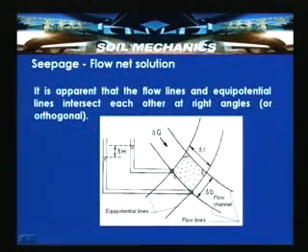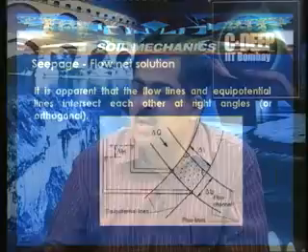So, here the drop which is taking place for a distance delta L for flow to take place is around delta H. So, we can also say that the hydraulic gradient is now delta H by delta L. For steady state seepage conditions, i is equal to constant. Here, this is the total head for this equipotential line, and this is another equipotential line which has experienced a loss, that is the total head is less by delta H. That means delta H is the head loss which has taken place between these two equipotential lines.